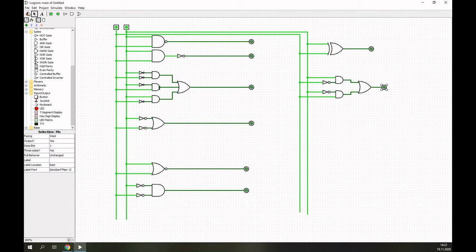So, and let's have a look now if both of these outputs reacted the same way. So we have 0, 0, we have a 0. If one of these is 1, then we will have an output of 1. And if both of these inputs are 1, then we have an output of 0. So here is the XOR. This was the NAND, this was the NOR, this was the XOR. So let's come to question number 3.